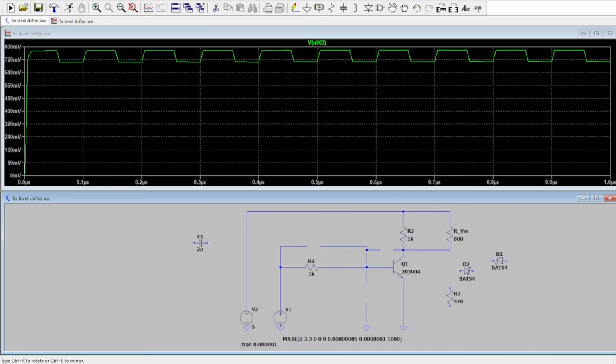I did some research and I found out that you should not drive those transistors into saturation at higher currents. I tried out using Schottky diodes right here and there. Did not work exactly the way I wanted it to. It made some improvement, but not as much as just adding this resistor right here. This resistor builds a voltage divider which reduces the voltage present at the base of the transistor, but it also provides a path for the current to sink through the transistor to ground.